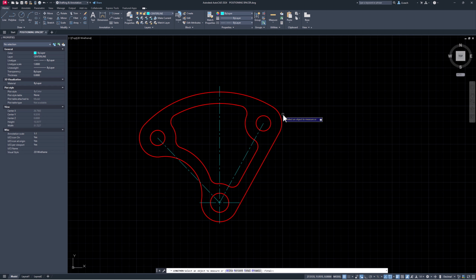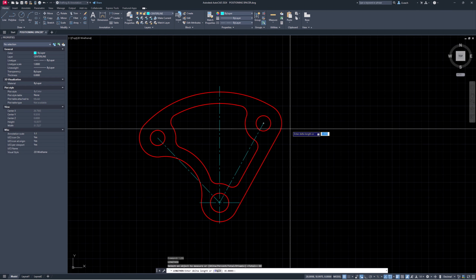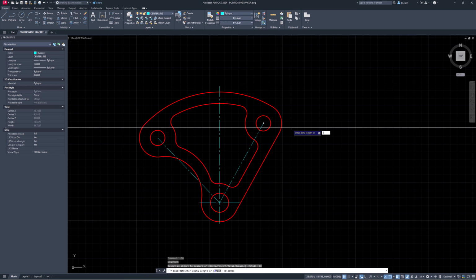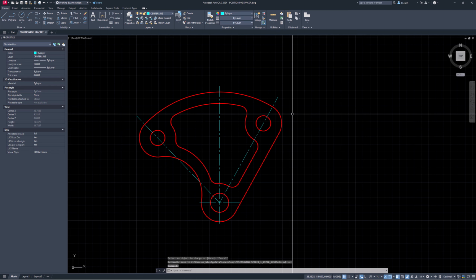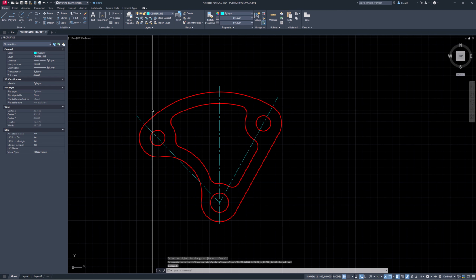Click on lengthen. I want to go to where it says delta. Click delta. I think I'm going to select for my length. Let's try 1, enter 1. Select the end of this. I probably needed 2. Will that work? Click the end of this twice. So once, twice, that's all I need. Yeah, so it extends a little bit past there in those directions.